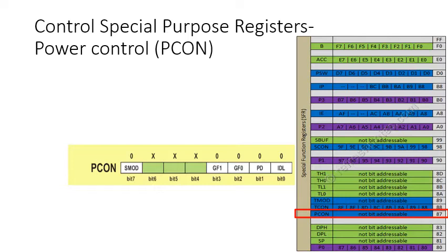When the microcontroller comes back to its normal mode after the reset, the values of all the special function registers are lost, but the data in the general purpose RAM remains the same. In the case of idle mode, the most power hungry unit, the CPU of the microcontroller, is turned off. All other peripherals like timer, serial communication and interrupts keep functioning normally. Also, the status of the CPU, accumulator and stack pointer remains as it is. There are two ways to pull the 8051 microcontroller out of the idle mode: an interrupt that changes the value at PCON.0, or a hardware reset.